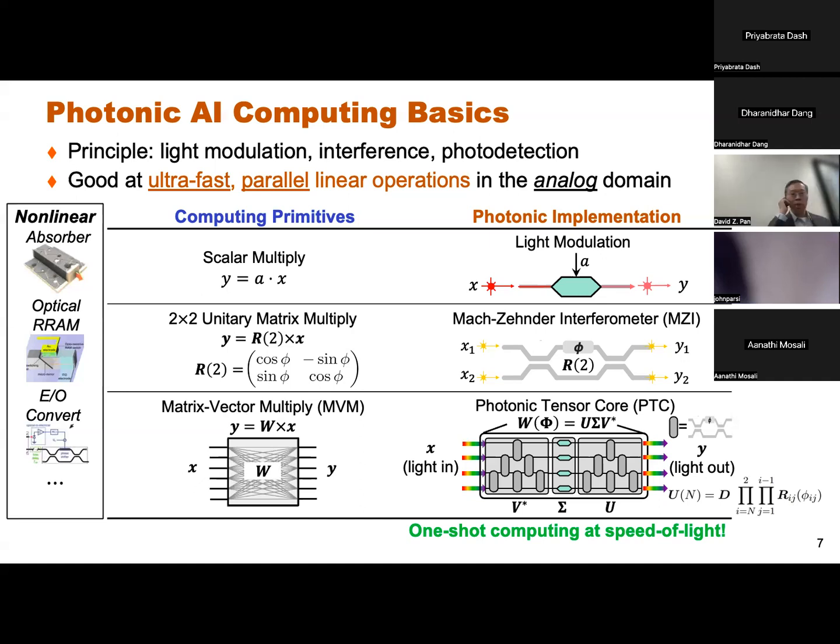So that's why I think totally replacing CMOS won't be practical. But nowadays silicon area is in general cheaper, and if you work on computer architecture, people are even talking about dark silicon, because if you have so many billion transistors all turned on, man, your chip will fry very soon. So in that sense, you can have some pretty big area dedicated to optics. If they consume very little power, then, hey, go for it, right? If you can get thousands of times improvement in all these PPA metrics, right?